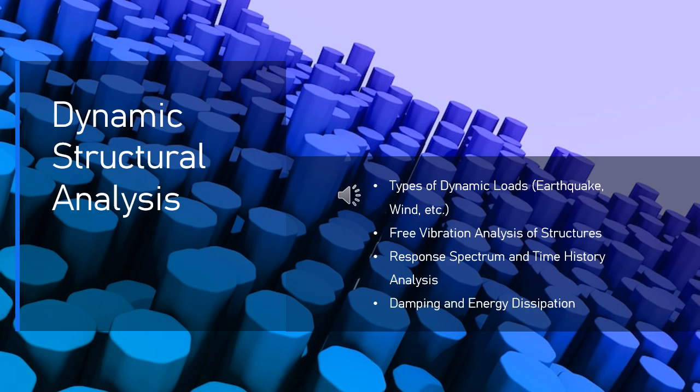2. Coulomb, or dry, damping. This type of damping is caused by friction between two surfaces. The damping force is constant and independent of the velocity of the vibrating object, typically modeled as a constant resistive force opposite to the direction of motion.